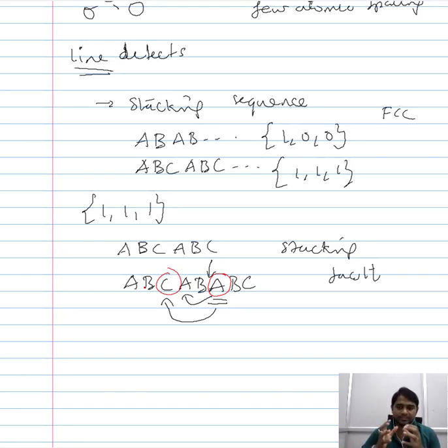It is not a defect that is associated with a given atomic spacing, but this is a complete shift in the arrangement of the atoms. And since the shift does not mean that we are replacing the whole of the atom, but is just a small change in the position of the atom, we refer to this as the stacking fault, and we categorize this not under the area or the surface defect, or the volume defect, but under the planar defect.